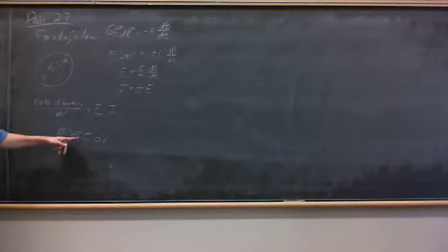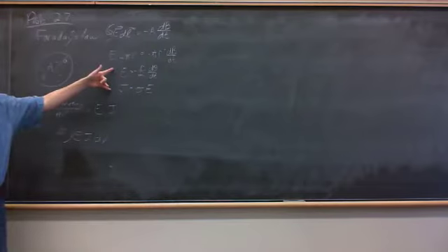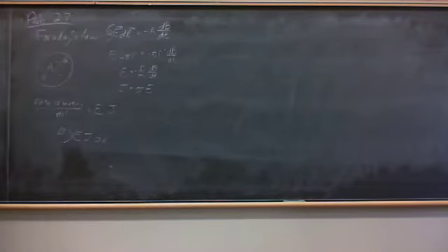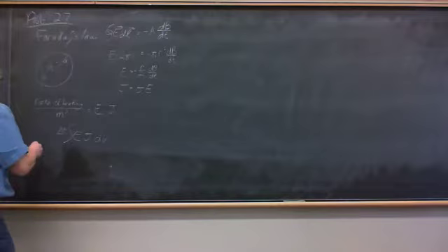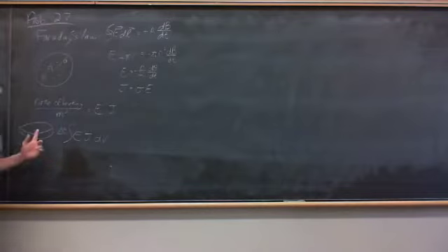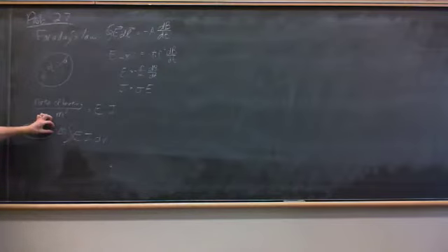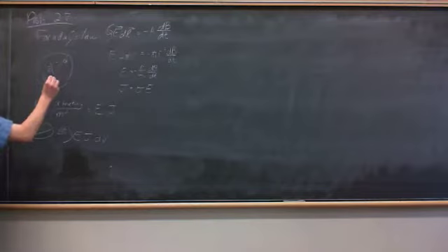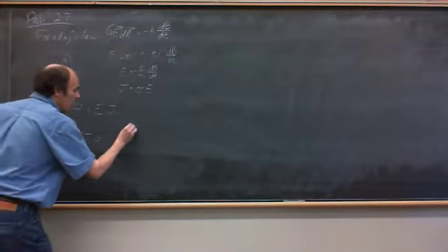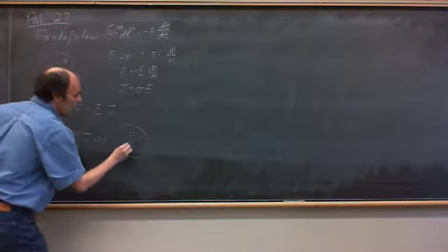So this is going to be E times J, which you got in part A. To integrate over the volume, well, this electrode really is like this. It's got some thickness to it, and nothing depends on the depth. So the dV has a term that's just the thickness. But then you have to integrate over the cross-sectional area. So that requires a little bit more complicated thing. You end up integrating one of these things.